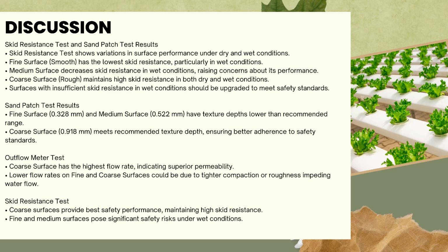The sand patch test shows the significance of texture depth for skid resistance. The fine surface at 0.328 mm and the medium surface at 0.52 mm fall below the recommended 0.65 to 1.25 mm range, compromising grip and safety, especially in wet condition. The coarse surface, which is 0.918 mm, meets the standard, ensuring better safety and adherence.